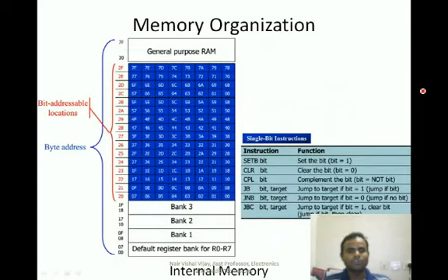Okay, so this is the memory organization for the bit addressable area. Now, if you see the bit addressable area, you have around 16 bytes of it. In these 16 bytes, each bit can be addressed, and the address is given here as you can see on the screen. It starts from 00 to 01, 02, 03, 04, 05, 06, 07. This is for memory location 20. So the 8 bits in this single bit addressable register can be accessed individually using some instructions,